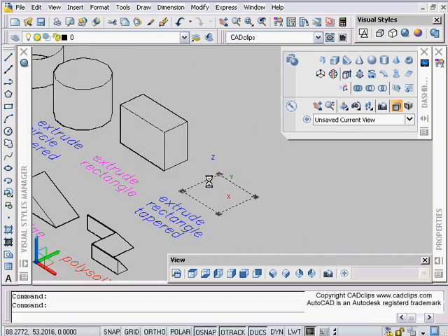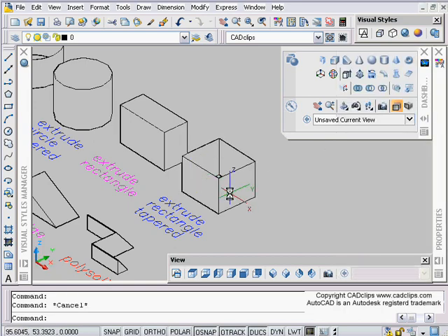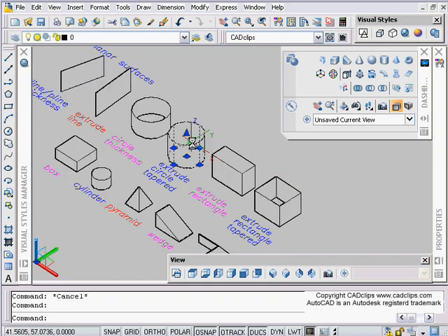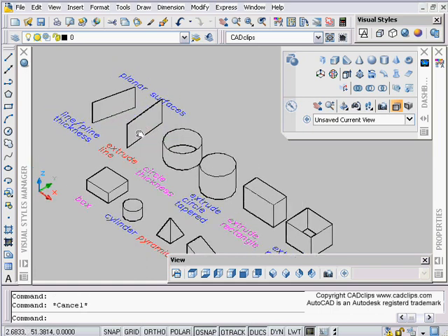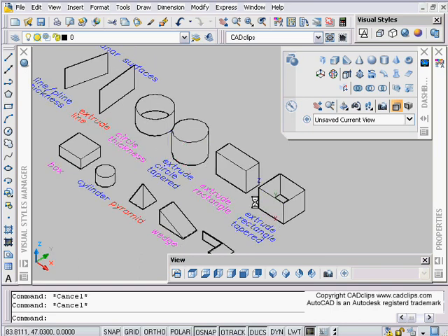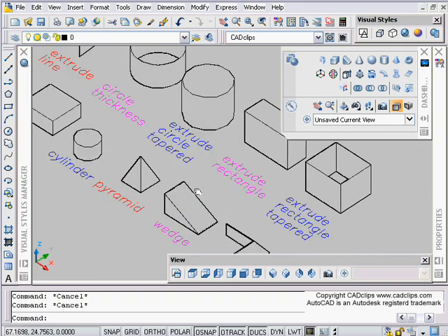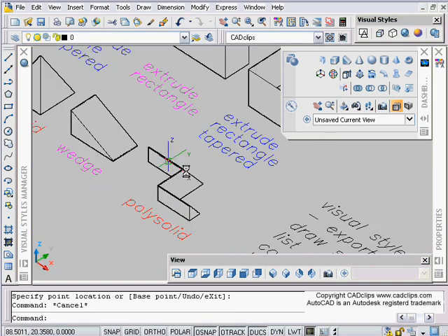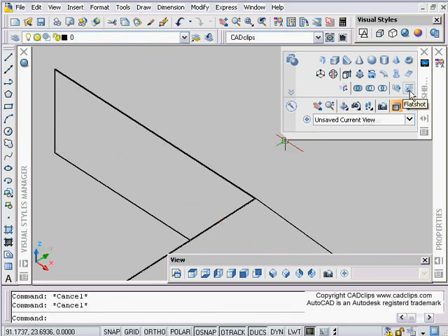Now I'm going to double click on this polyline, or click once maybe, go to my properties, and give that polyline or rectangle a thickness of 10. And that goes up. You'll see that thickness with polylines and circles don't put a top on it. Extrusions do, of course, here, and then align with the thickness. And you could also do the same thing with an arc. So just getting used to looking at these and recognizing what they are and how they operate and the differences between the objects. This here is a polysolid, of course, which has the grips that work that way.